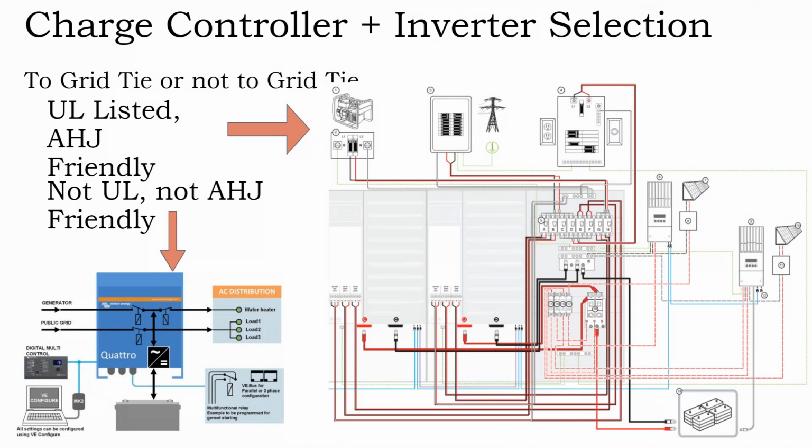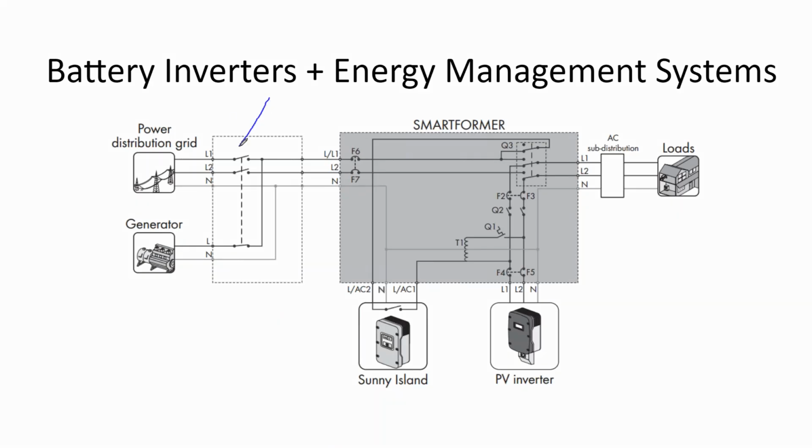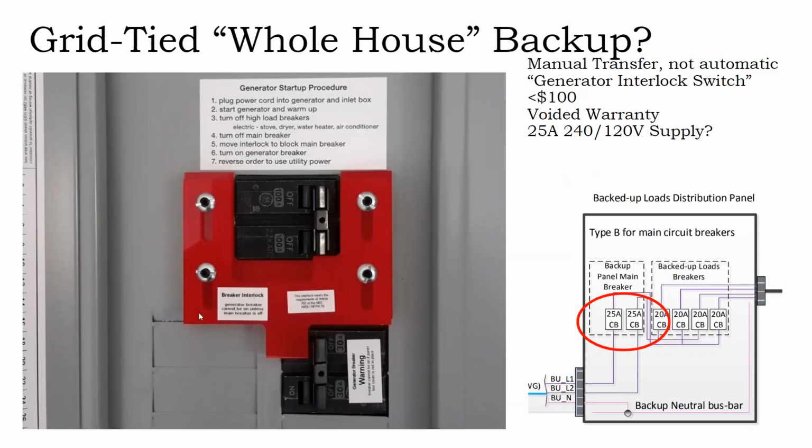Rewiring an electric service panel can be 10% of the budget of a solar array, and you're not getting anything but just relocating circuits from one side to another. That said, having a transfer switch for the entire house is very expensive too. And so one component that I think is going to be increasingly popular is to put a manual switch, because this is like $50 compared to a whole house 200 amp automatic transfer switch, which is $700 or $800.